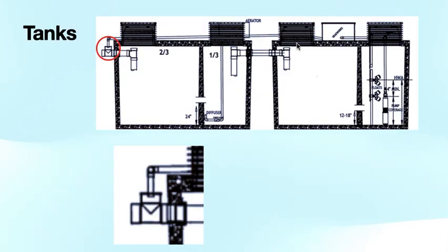So again, repetition is key. This vent line that's going across these 2 tanks is going into this 4-inch T that's going to be spliced on the outside of the tank on the inlet going into this initial tank. This 4-inch sewer T that's pared down to 1-inch PVC up here is pre-made and comes with the kit. So you don't need to make this, but this is where this goes, right at the beginning of the system.